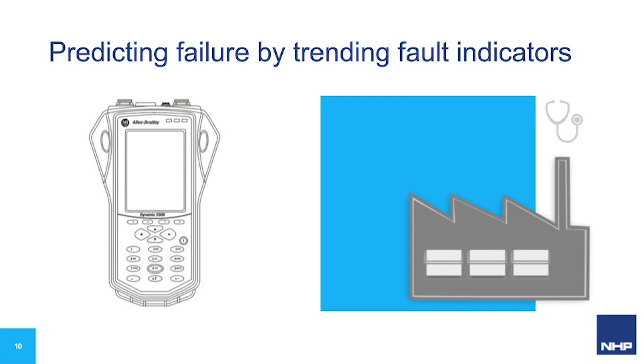If we go one step further and talk about how vibration data is actually collected and analyzed, generally sites have their own reliability team if they're big enough and it justifies that, and they collect and analyze data. Some sites have to use condition monitoring service providers that collect data, say every 12 weeks at a shutdown. And data collection is gathered manually using a portable handheld meter and then taken back for analysis.